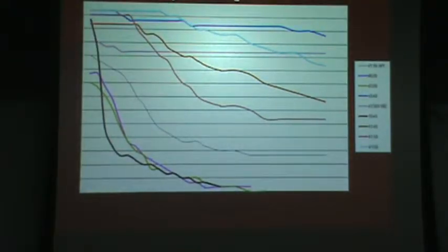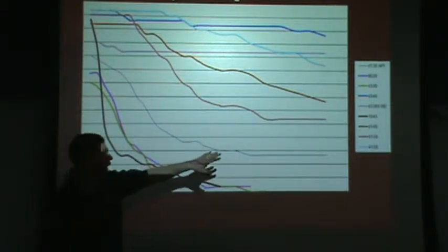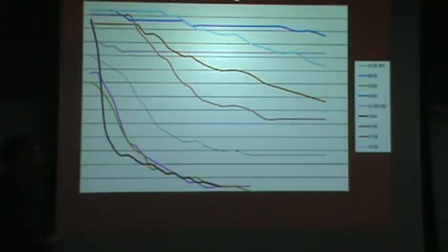So here is some examples of the kind of results you would get. So we've got, I don't know, about 8 or 10 different alloys and actual Jominy data from these individual alloys. So you can see what the range is. We can see a couple things. First, that some materials in the as-quenched condition, so at the position number 1, are relatively soft in comparison to some of the others, right?